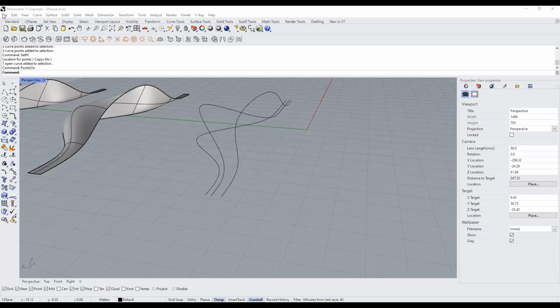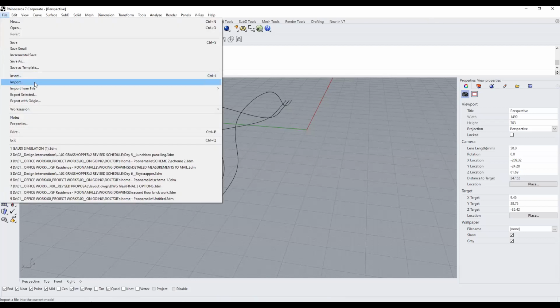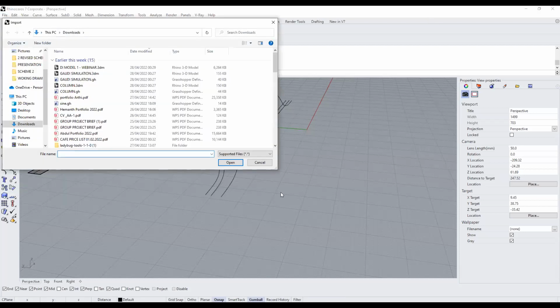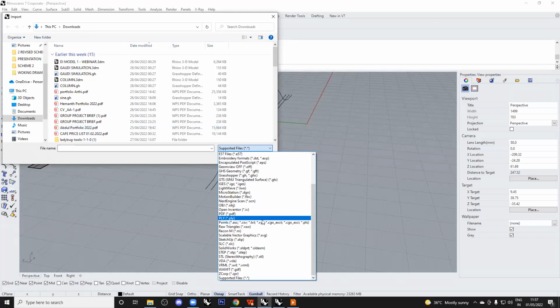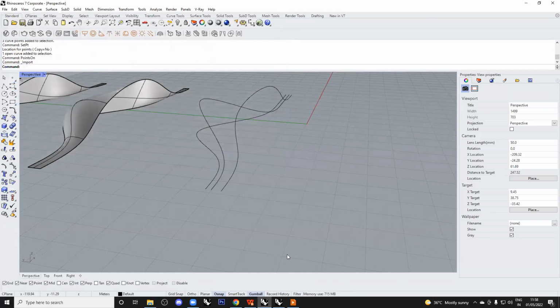And after you do that, go to file, choose import, and under import, choose the format. You can see that all of these different formats will work. You will most likely import it as an OBJ file if it's from 3ds Max. If it is a SketchUp file, you can directly import it from SketchUp. That's it. And yeah, that's how you go about trees.